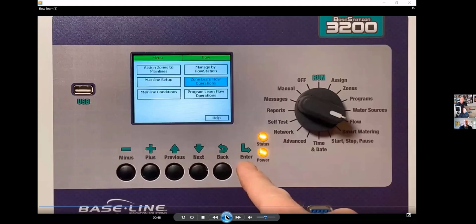Because what would happen is if somebody had changed that K value, you might be expecting 50 gallons a minute and it's throwing 120, and that's not accurate because the K value is not in there correctly. So having that right one is important.